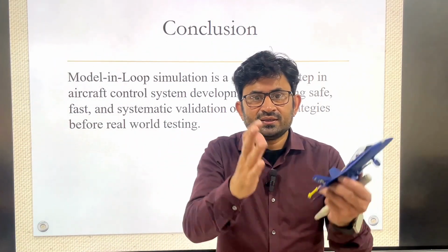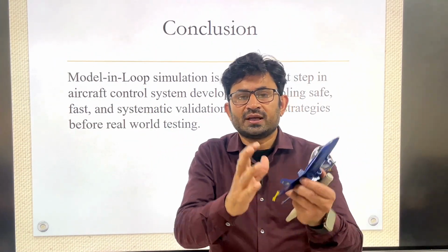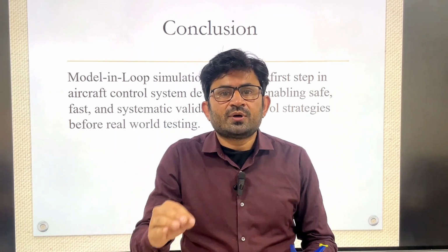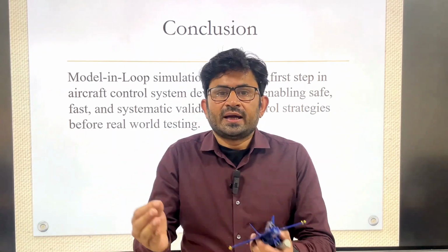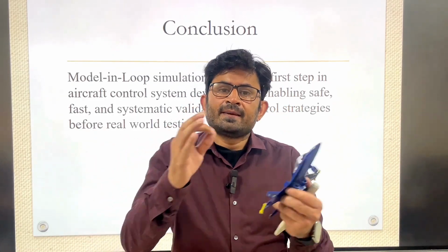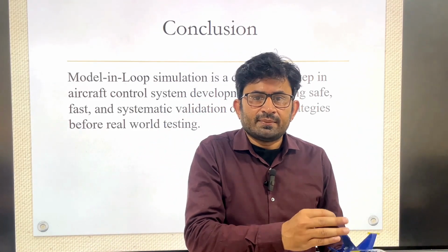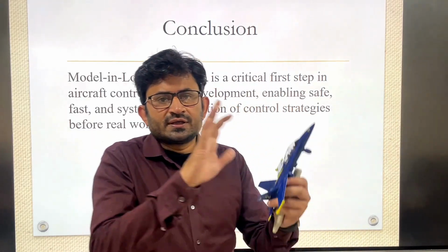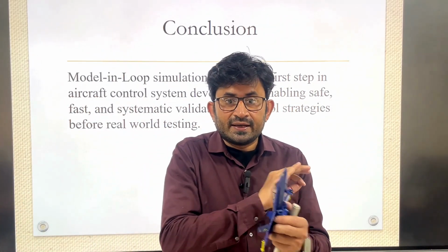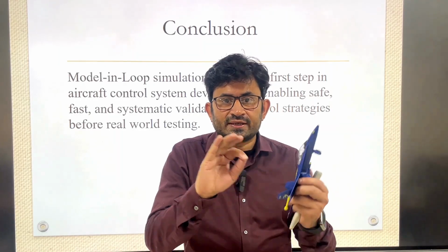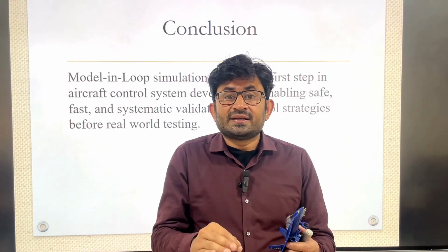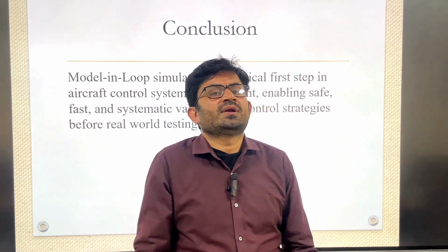So in Simulink, or any other software, you have to model everything: the aircraft, in the aircraft all the non-linear models or other effects, and in the controller you have to model everything, sensor noise, hardware delay model, I mean to say. So everything you can actually model, and once it is ready, the code is ready, the simulation is running, then you will complete the first step for controller design.